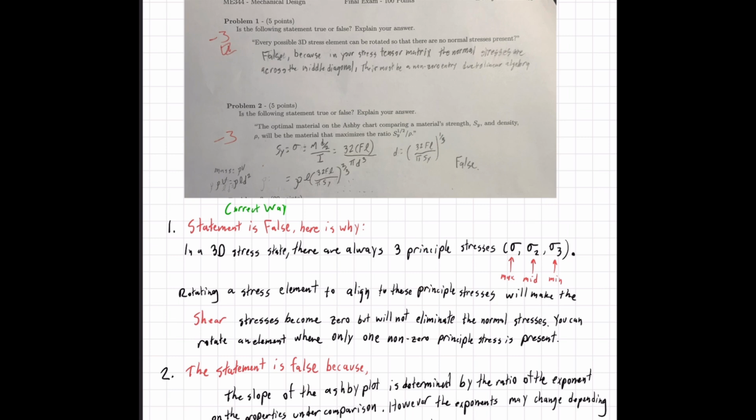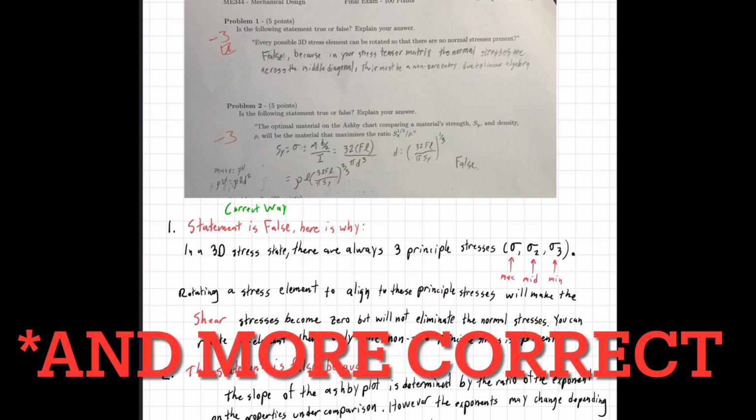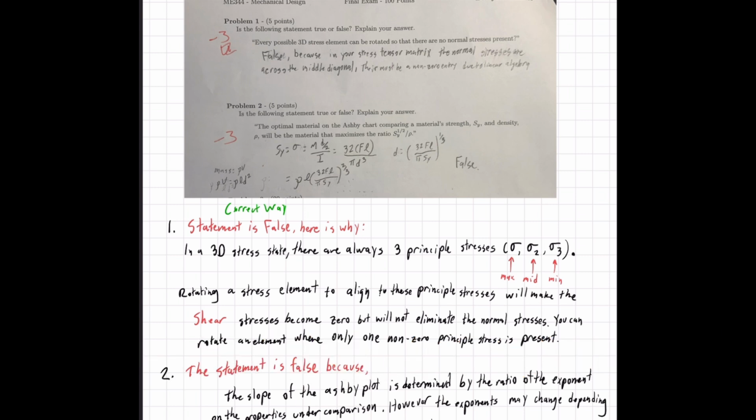This is wrong because there's a different reason that it's false. In a 3D stress element, there are 3 principal stresses present: sigma 1, sigma 2, and sigma 3, where sigma 1 is your max, sigma 2 is your middle, and sigma 3 is your minimum principal stress. But rotating a stress element to align these principal stresses will make the shear stress 0, not eliminate the normal stresses. You can rotate a stress element where only one non-zero principal stress is present. And this is the correct answer.